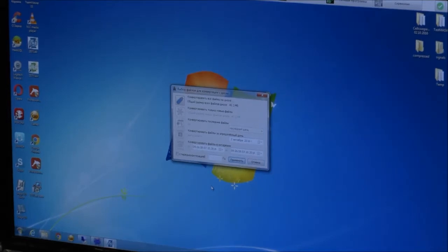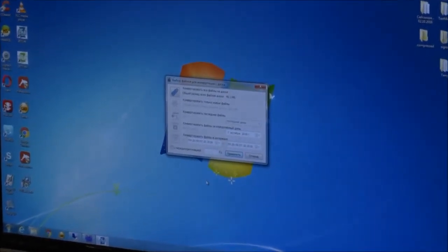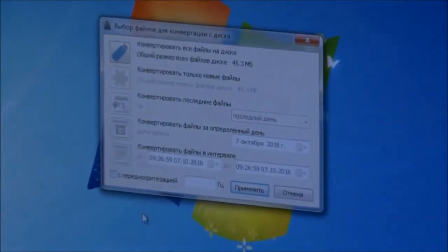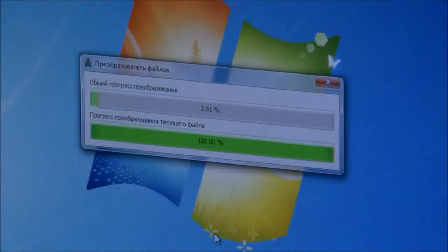However, since the data was recorded at sampling frequency of 200 Hz, we will have to change the sampling frequency value to a higher one. For instance, to 1000 Hz. We select the sampling frequency change option, enter the value and click Apply key. Here we can see data conversion process. Data conversion process is performed in Trends view mode. So finally we shall have Trends records file.